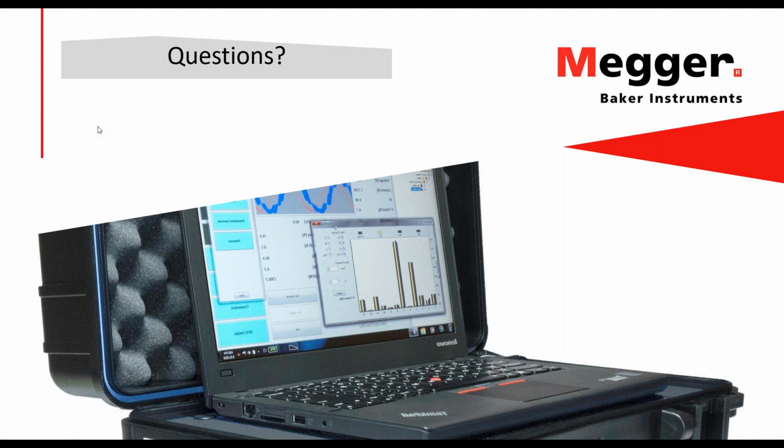Nameplate speed. So technically we need horsepower or kilowatts, the voltage, speed, current of that motor, and if it's not a VFD, whether that nameplate information is for a 60 hertz motor or a 50 hertz motor, is essential for being able to interpret the results.